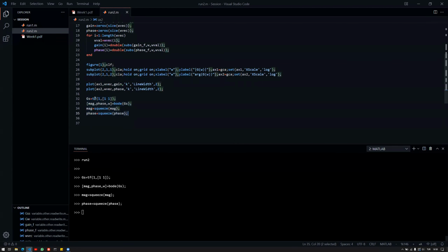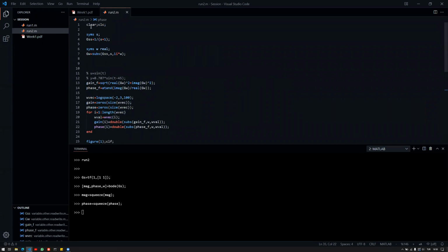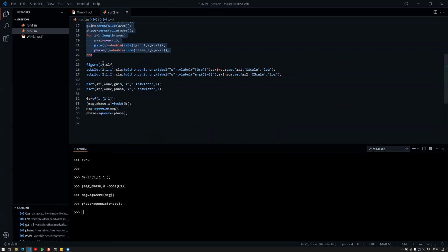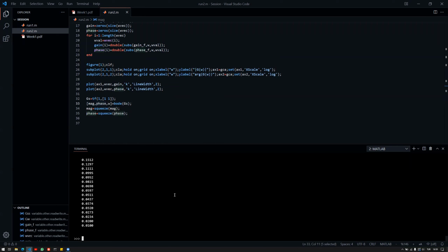So with this small piece of code, you can skip the whole calculating from scratch part, but you can use the same plots. Combining these lines of code, you can generate the exact same bode plot. This will have some advantages when we cover the frequency domain methods, because we can annotate and manipulate the data that is already calculated into mag and phase. Let me show what mag has, what phase has. You have basically frequency, phase, and magnitude. You have everything you want from a bode plot. If you omit that and just call bode, it will generate the plot.